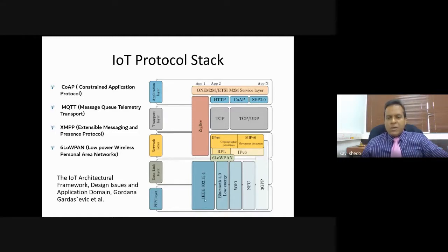You see, most of our sensors use 802.15.4. Then it goes through this 6LoWPAN. Then in the upper layers you see TCP/IP, where we use HTTP and everything. But then at the top here, you notice CoAP. This is for the data management.